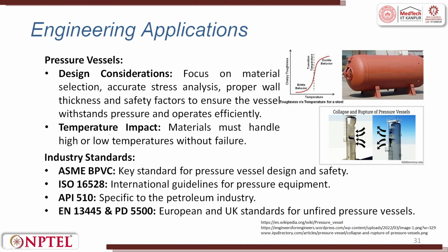So where is it exhaustively used? We use it in pressure vessels in the design consideration. It is focused on material selection, accurate stress analysis, proper wall thickness and factor of safety to ensure the vessel withstands the pressure and operating efficiency. The temperature impact is also high. The material must handle high or low temperature without failure.